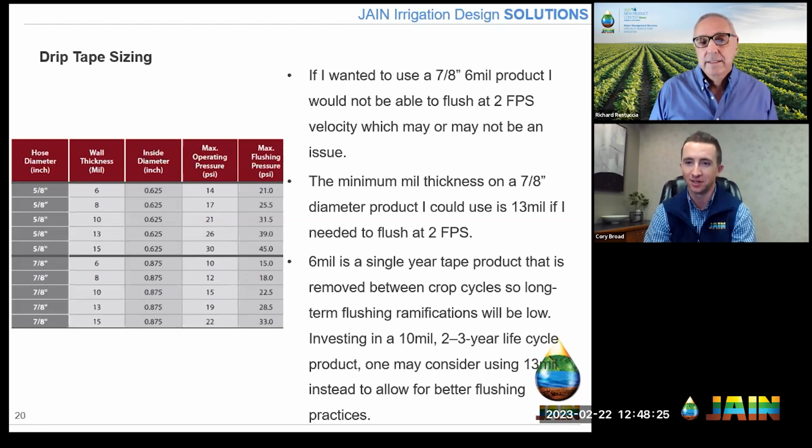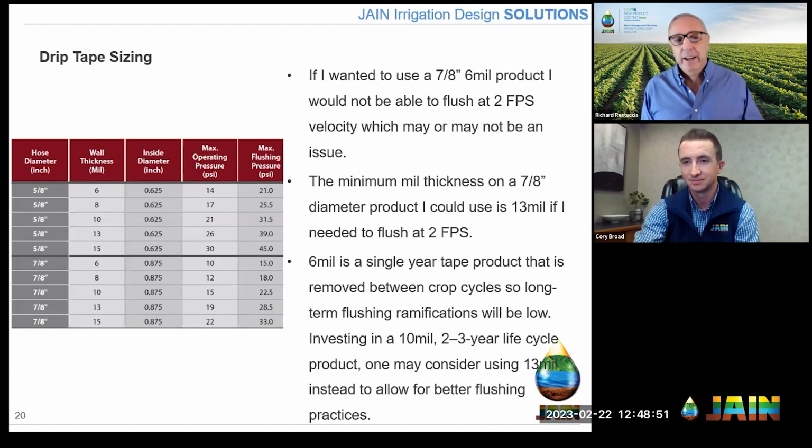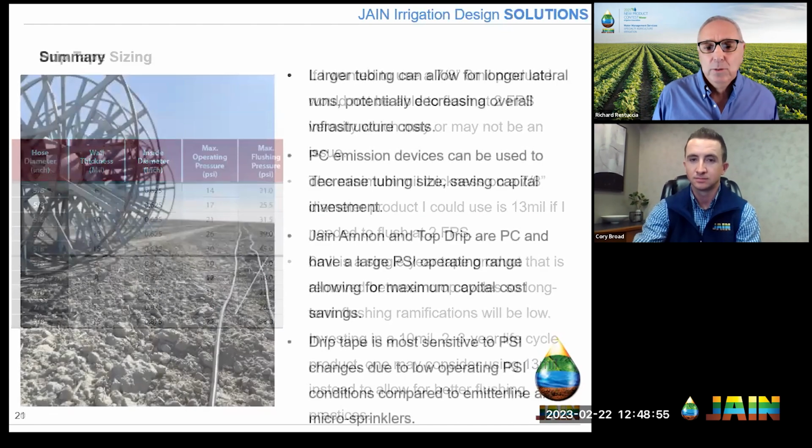And procedures are duration and timing and velocity, right? If you can go through how often do I need to flush, how hard do I need to flush that system, and how long do I do that for? If you get that right, you won't have those examples that I just showed. Yeah. And the air vents, one of our most popular trainings, certainly maybe surprising to some that it was so popular, but the right vent and the right placement is key. And you did a really good job getting those points across.